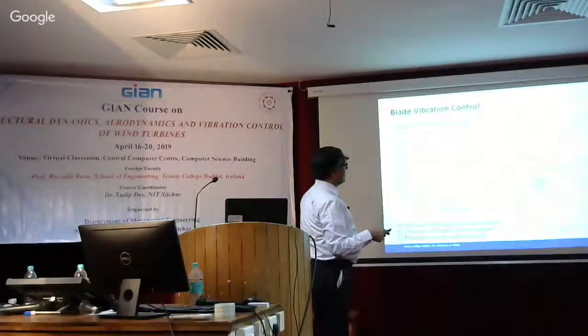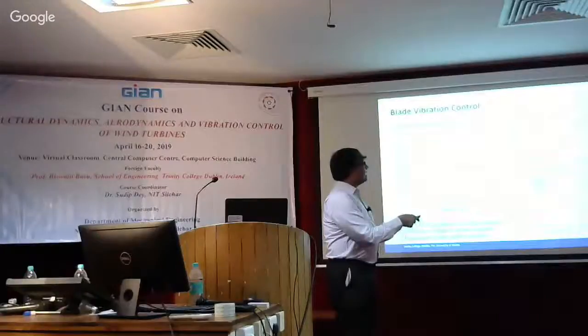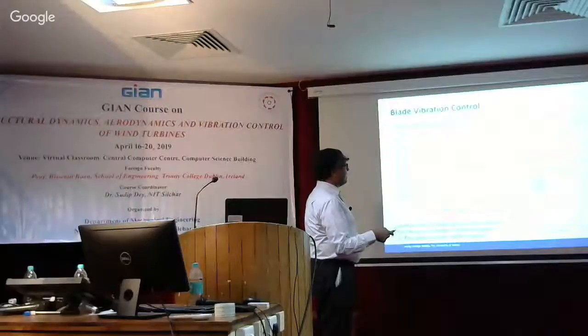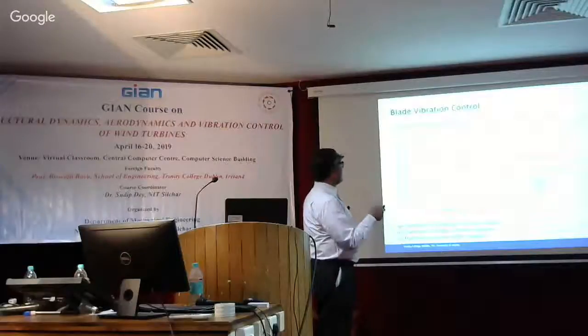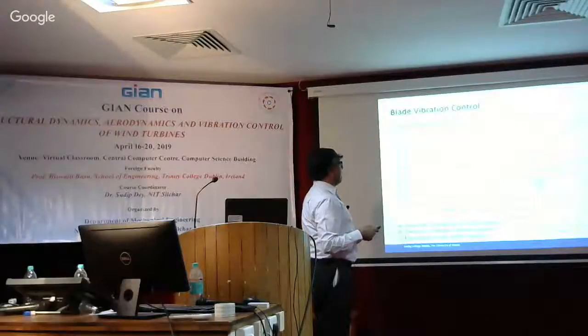So this is the gamma value which is decreasing, meaning the force is increasing actually. This is the weighting function we have used for optimization. So gamma decreasing means the actuator force is increasing. Obviously the blue is no active tendon, red is slightly less, and then the highest value. So when you have a large force with active tendon, you get 90% reduction, but with a small force you can get up to say 50% reduction in this case. And what we do now is look at the in-plane response, and for example here you can see the variation with the different loads.